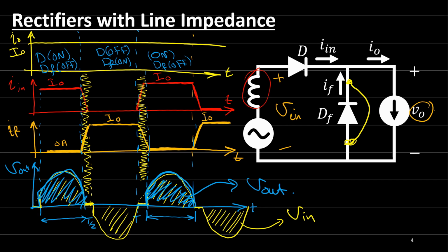How to calculate the average voltage for this rectified output? You need to find the commutating time. So we need to find when this voltage hits this value, or when the freewheeling diode and the main diode will be released from both being in conduction mode.